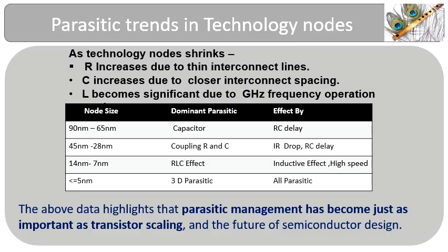At these advanced nodes, switching speeds became so high that inductive effects could no longer be ignored. Key challenges at these nodes are ringing and reflections caused by parasitic inductance in global interconnects and clock networks. It also led to increased EMI and self-heating phenomena.